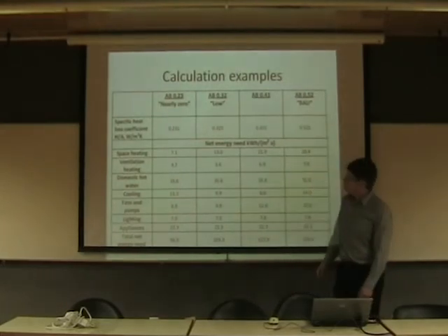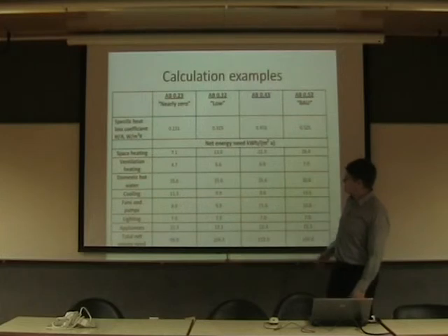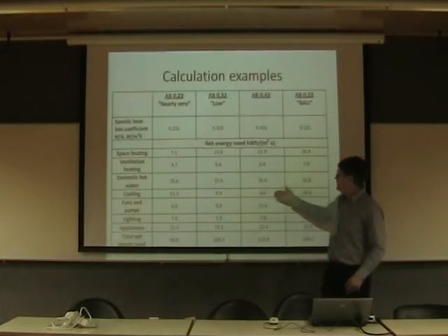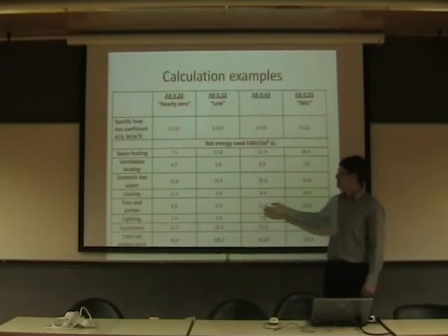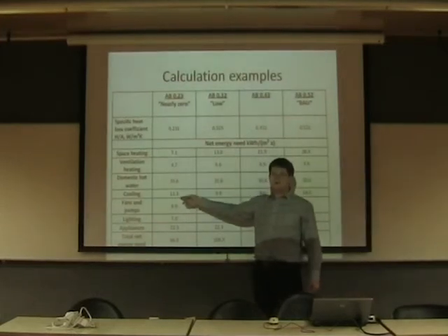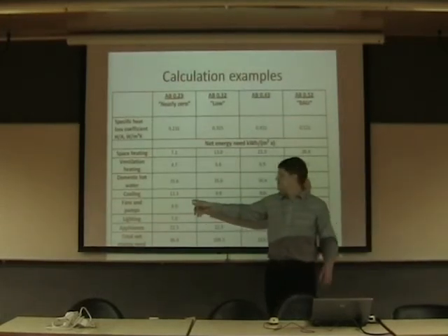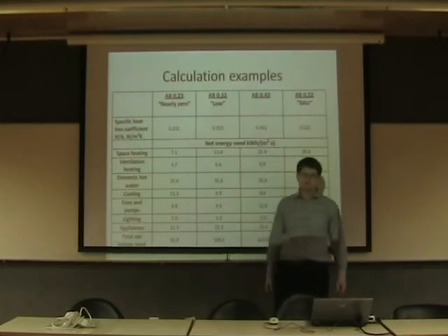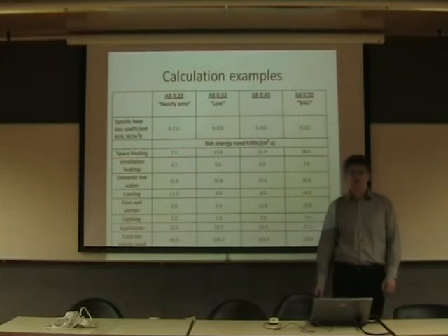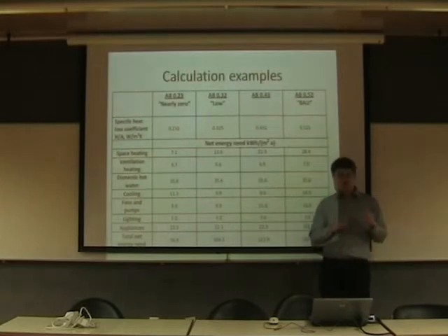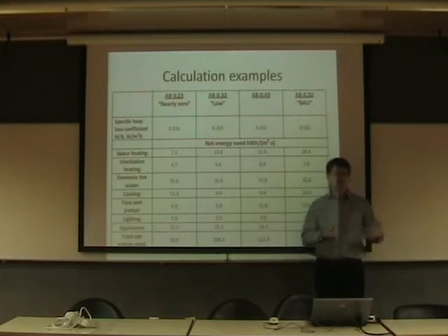But we can also see that with the regular building or the low energy building, we don't have much need to cool these areas. But with nearly zero energy buildings, we must cool more. This is 11.3 kilowatt hours per square meter per year. We must cool down this area because Estonian law says the temperature can rise above 27 degrees for only about 150 hours.